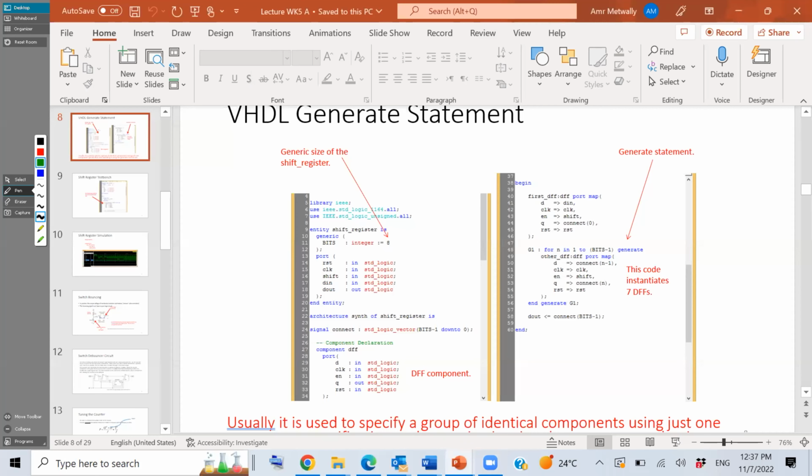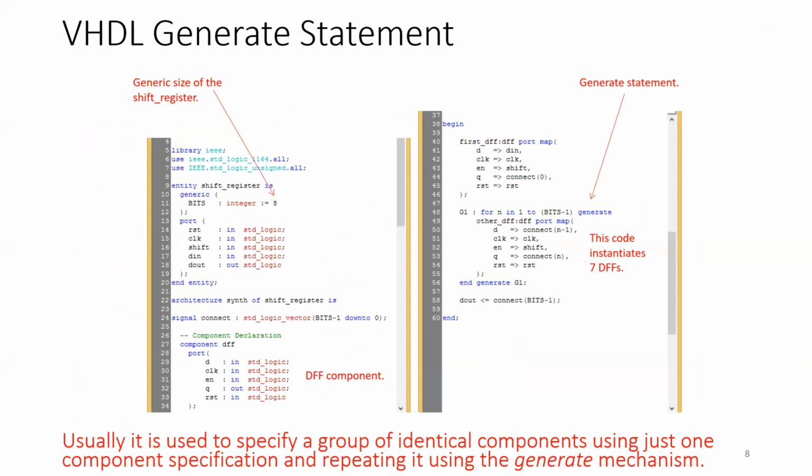Yes, okay, so you see how in your component declaration, it says component is DFF, D flip-flop. If I was to use one of the files that I created for a shift register, would I type the name of that entity there? It must be called DFF. Oh, so component must be DFF regardless. Yes.